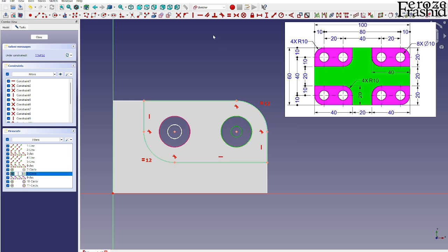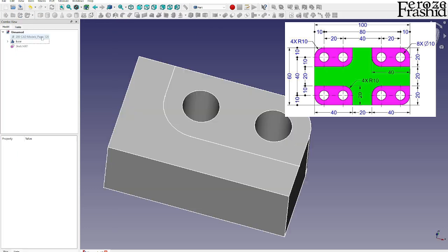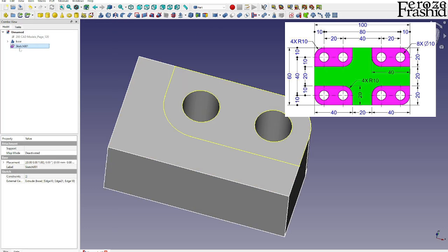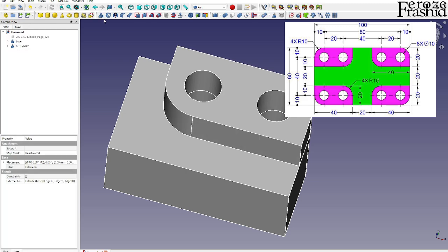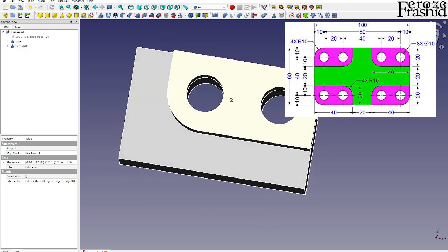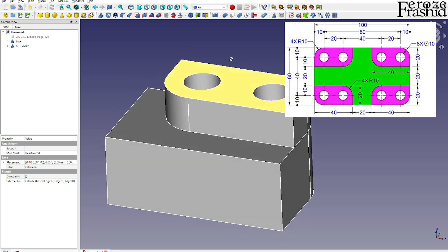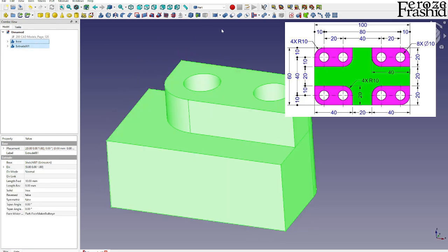Keep going. So this would be the same, and obviously this would be the same. So there it is. That's our sketch. Let's say extrusion from our base and extrude that for 10 millimeters upward. So that's our through holes and 2 levels of sketching.